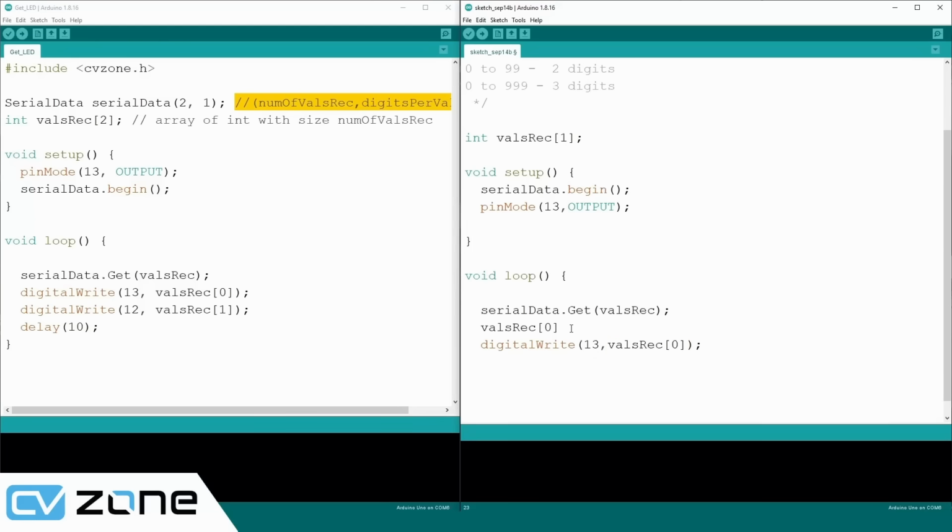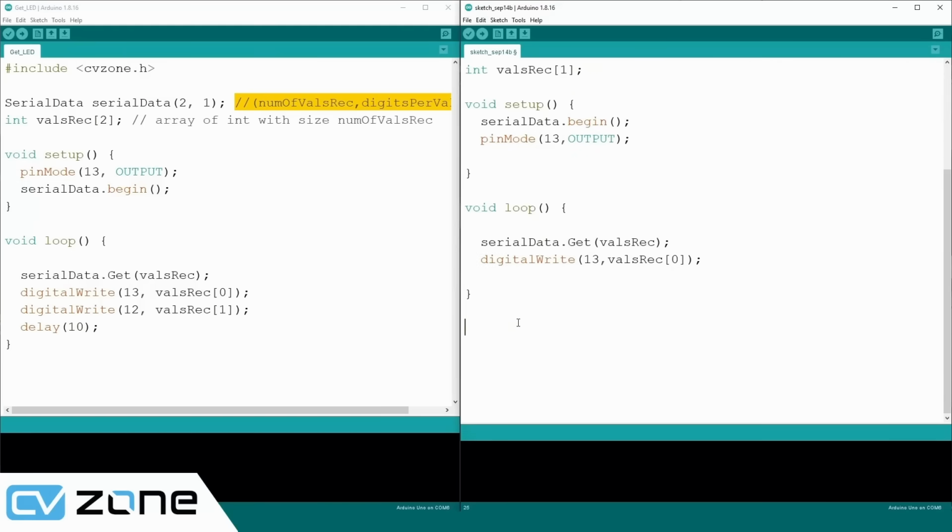But right now what we will say is get it from the Python code, and then we will decide whatever the value is, we will send it here. So from Python, we can send our value directly here. What happens in the Python code is basically it sends a string. A string will be something like this: it will start with a $, and then there will be 0 or 1. So if we want to send one value, we will write it like this. If we want to send 0 value, we will send it like this, because it is 1 digit.